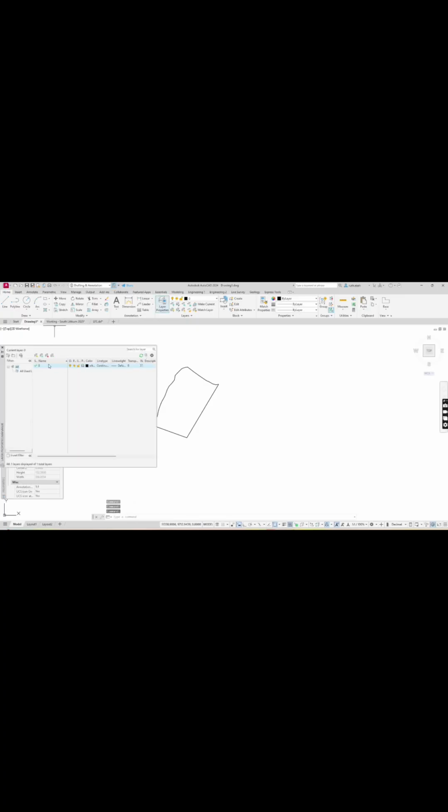The next step now is to create layers. I'll be importing the back points, which is for the roof of the mines. I'll also import the seal points, which is for the bottom or the floor of the mines. The topo points are already here. And also the wall, I'll be building a wall, and I want this wall data to be stored in the wall layer. This is just to keep your work organized and clear.